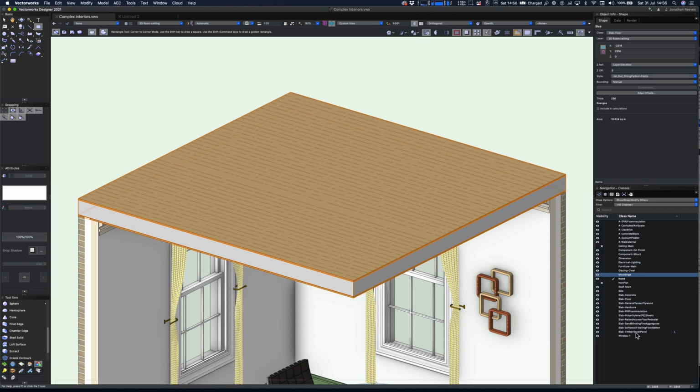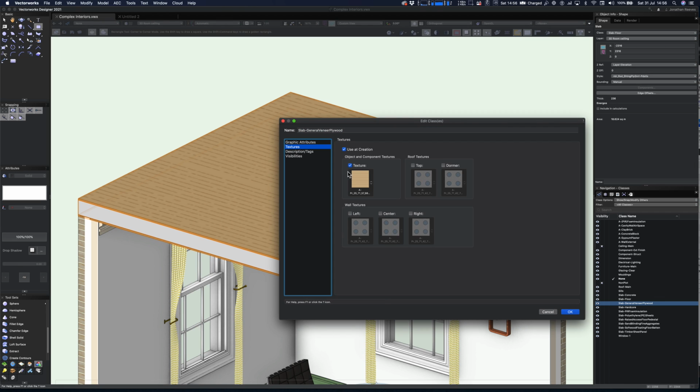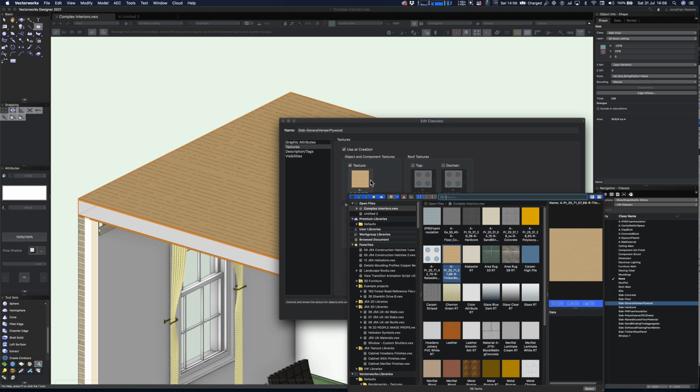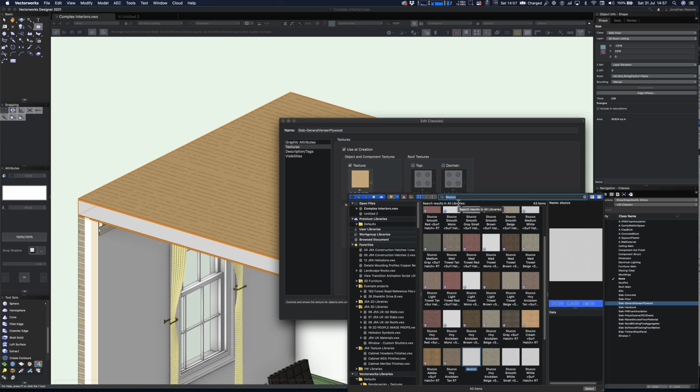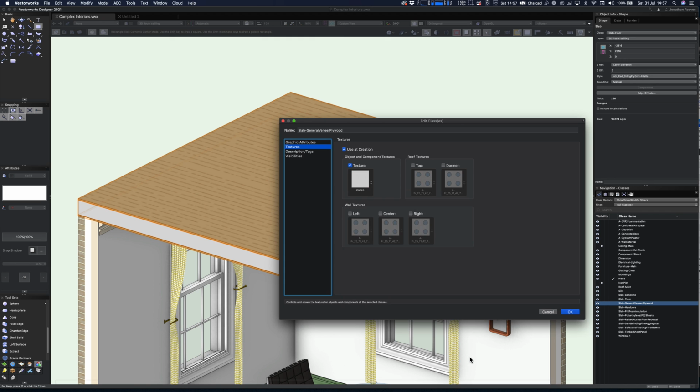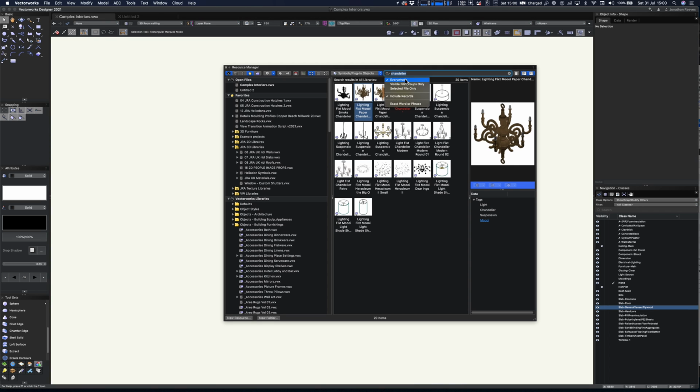The final thing then is to edit the class that's giving it that brown fill, which is obviously a floor finish at the moment. So I'm going to edit that, pop in there, and could turn the texture off if I wanted. But you know what? Let's go for a white plasterboard type texture. And if you're unsure, the American term stucco will help you find plasterboard as we would know it in the UK, or white plastered ceilings. There's lots of different types of stucco, but we'll go for a nice plain white one.